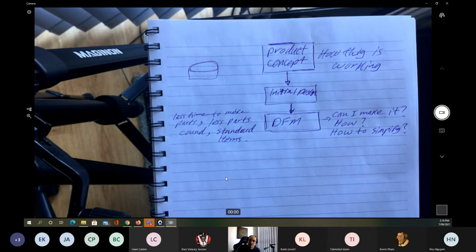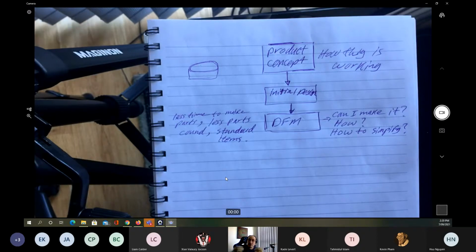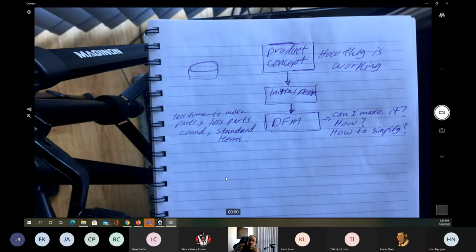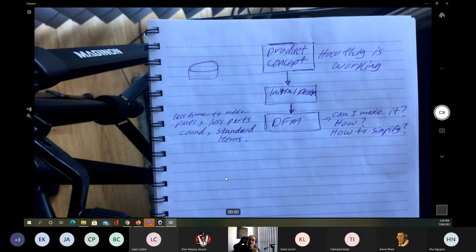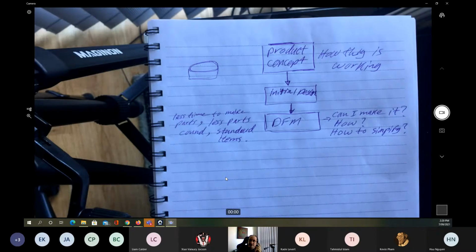with the plastic mold injection. So I can make 10 parts in 1 second. Or I can do the plastic casting. Okay, then I can make the valve in mass production. Maybe I can have a tray, and this tray has multiple cavities for the foot valve and the main valve, filled with the plastic, and then take off the valve and use it directly. Boom. I did a design for manufacturing. I standardized the items. I reduced time for the manufacturing. I'm only going to make the tray by having one of the valves. I can make one of the valves and use this one as a pattern to make the multiple valves.